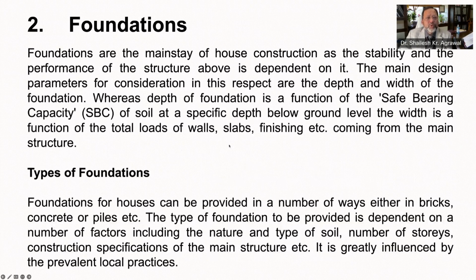Now let us come to foundations. Foundations are mainstay of house construction as the stability and performance of your structure depend on it. The main design parameters for foundation are its depth and width. Normally, the safe bearing capacity of soil at a specific depth is estimated, and accordingly, depth of foundation below the ground level is fixed.